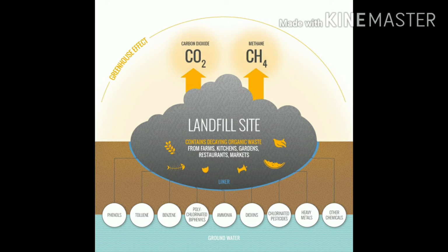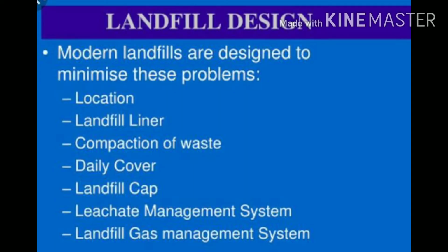The precautions while choosing the area of the sites for landfill is to minimize the cost of transportation. Landfill should be located centrally to the waste generation sites. Landfill area should be sufficiently deep to the surroundings as it can work for a longer period and hold huge quantities of waste. Where rainfall and strong wind is minimum, that area is suitable for landfill.